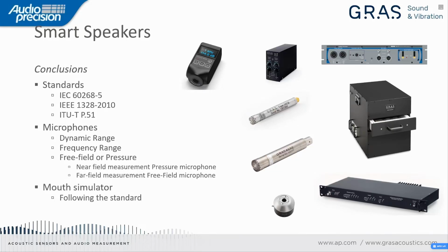In far field measurements, we have to use a free field microphone. The mouth simulator has to follow the standard. A test box is recommended if you have many production lines close to each other, so you won't disturb the different lines.